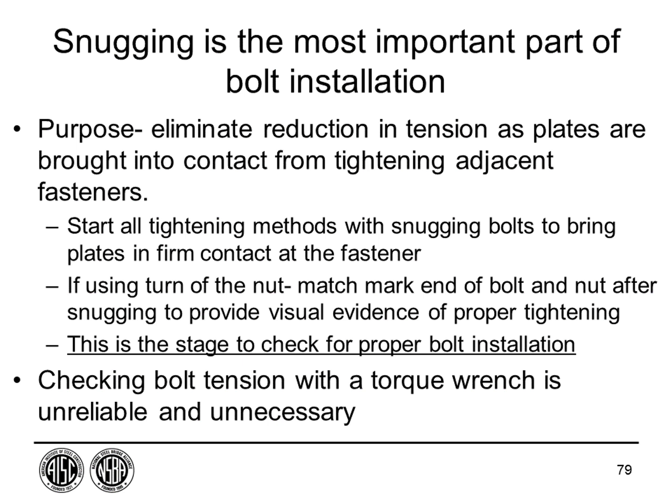The purpose of the snugging is to bring the plates in contact so that as you tighten adjacent fasteners, it doesn't loosen the snug fasteners that you started out with. We want to prevent the crosstalk between the bolts. If you have gaps between them as you're tightening the bolts down, it will loosen the adjacent one. This is the most important thing to do, and it's independent of the tightening method.